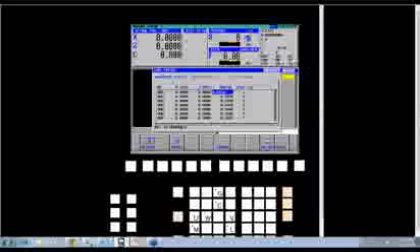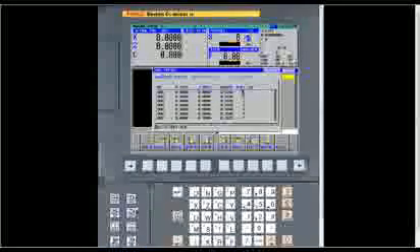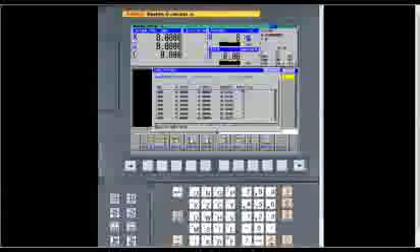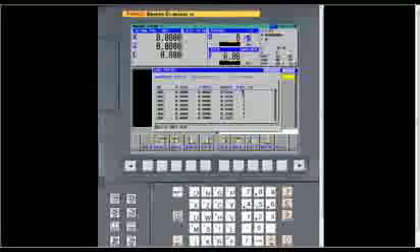The next one's very important also, the virtual tip, because what that's used for is the orientation of the tool. The ones you're going to use the most: a number 3 is typically going to be an OD turning tool. A number 2 will be an ID boring bar. A number 7 will be a drill. Those are going to be the 3 that you use the most. That's what you see on this first page, tools 1 through 7. We have a 3, 3, 3, 2, a 3, and then 2, 7. So typically that's what you want there.